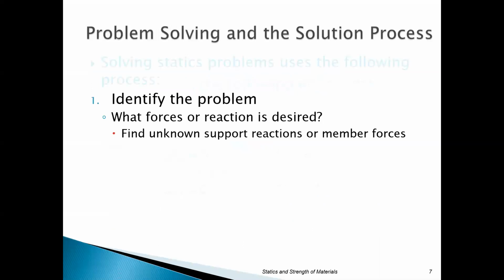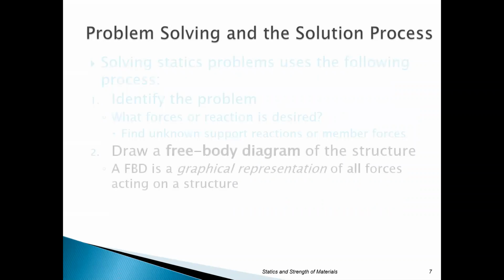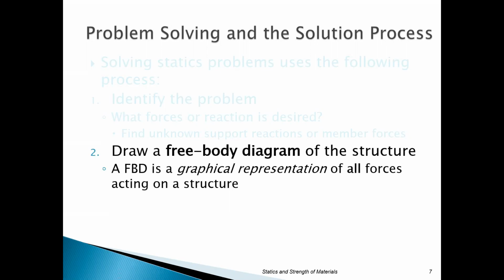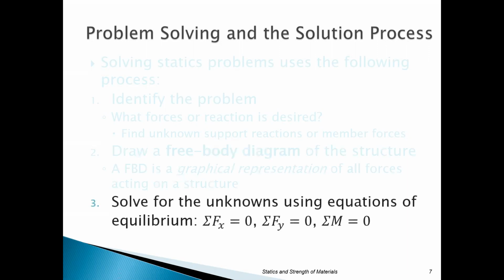So let's see. We said the first step in problem solving is you identify the problem, what forces are desired, what you have, what reactions. Then you draw the free body diagram. And again, that's so key. It's important. And then you apply equations of equilibrium, and you don't always use all three of these, okay? So it depends on the case.